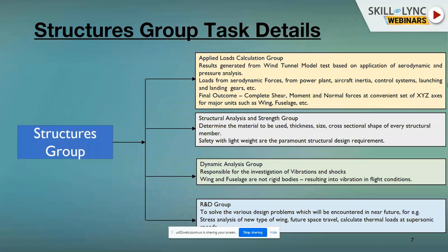It's approximately a 70% reduction in bolts, and a single bolt has a weight of around 150 to 160 grams. So if you consider a million bolts, that's a huge weight, which is resolved. That's why these days we have shifted from metallic to composite, from the structures point of view.